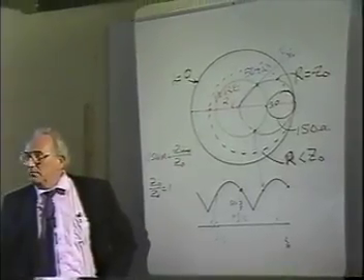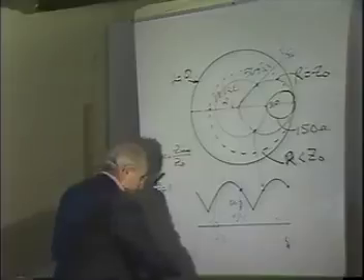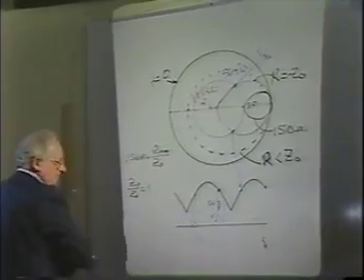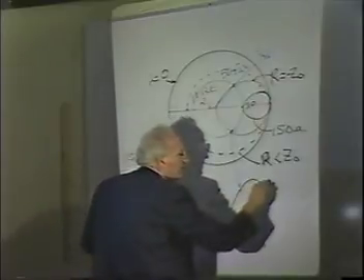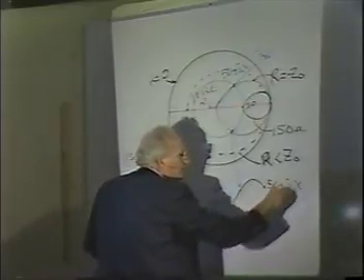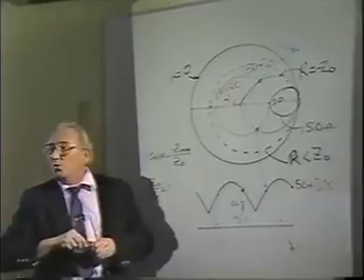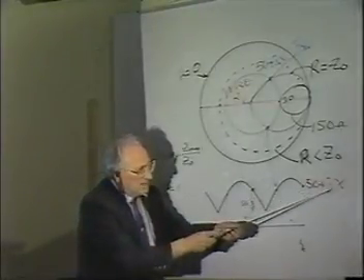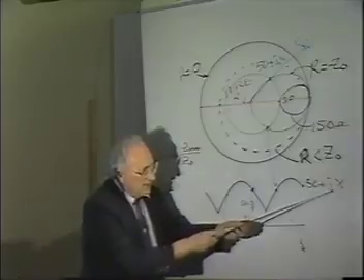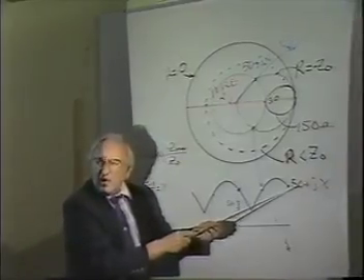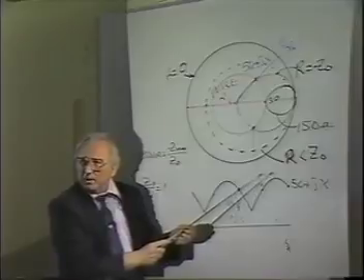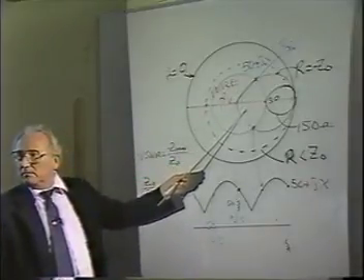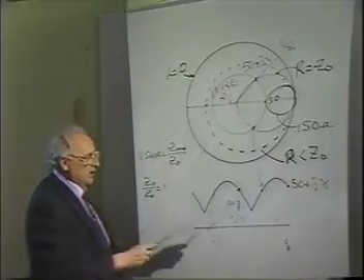50 ohms, right? That's the actual load. If I can take this load off, put a capacitive reactance of minus jX in here and cancel that, what do I have left? 50 ohms, right? Where does that put me on this chart? Right there, correct?